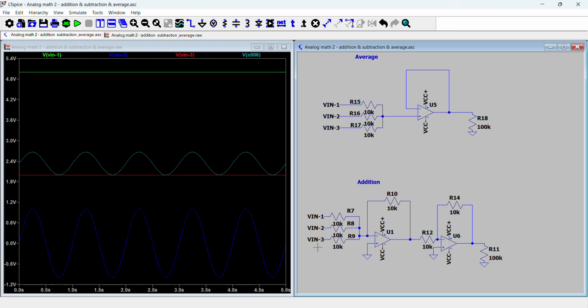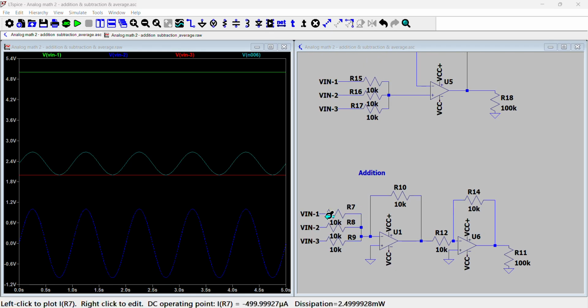The other way to do it is through the addition circuit, where instead of taking the average here, we ground the output terminal of this sort of averaging circuit. As you can see, because we add this op-amp here, the op-amp will make both terminals the same voltage, and this terminal is 0 volts here, so therefore this is grounded at 0 volts.